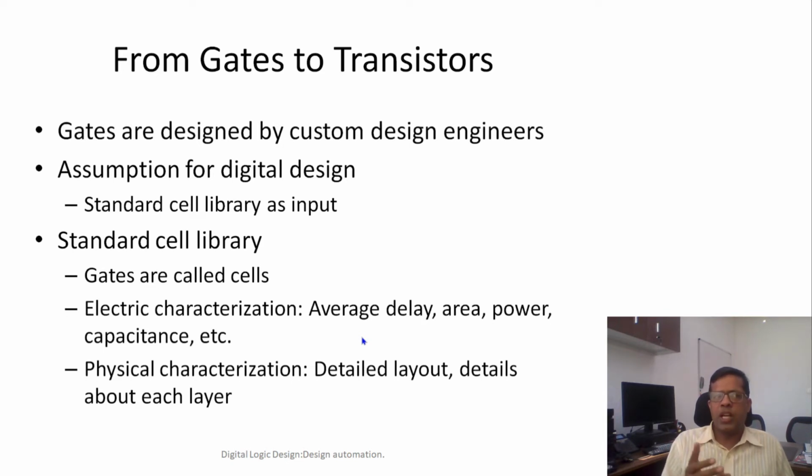For example, if there is a NAND gate, there would be a different design for a 2-input NAND gate, 3-input NAND gate, 4-input NAND gate. And similarly for AND and OR gates, there would be multiple designs. Further, because it's going to be designed by custom design engineers and analog design engineers, they will also think about what the load would be. So basically, one output of the gate, if it is going to multiple different gates, should be able to take care of the load capacitance.